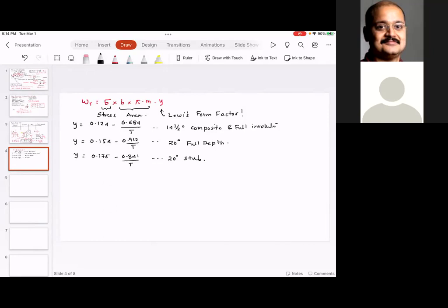Now, clearly, there are a lot of assumptions in this equation. The fundamental assumption is that when we look at the beam strength equation, the loads are not moving. But that is not the case. When the two gears come in contact, the loading is not static. The loading is dynamic. So clearly, we can't use the equations for static strength when you have dynamic loading.